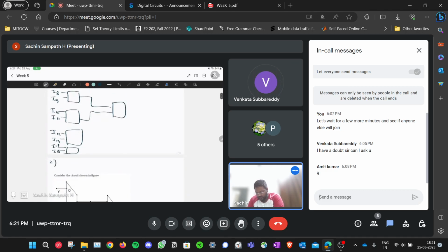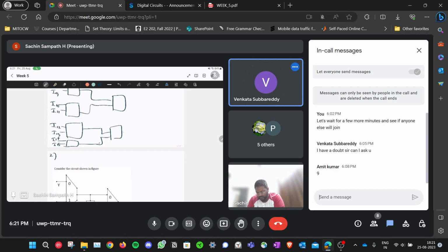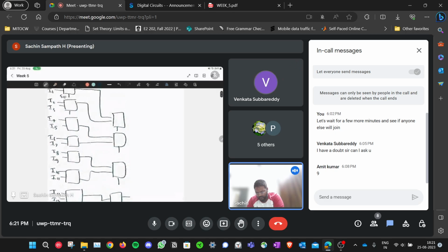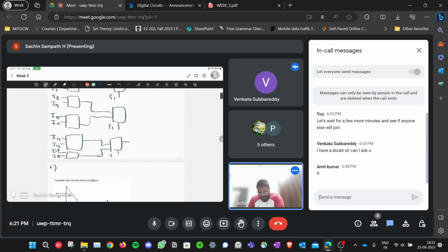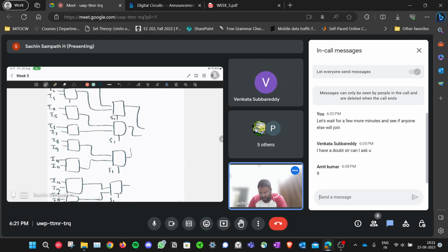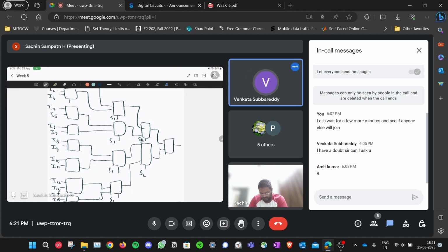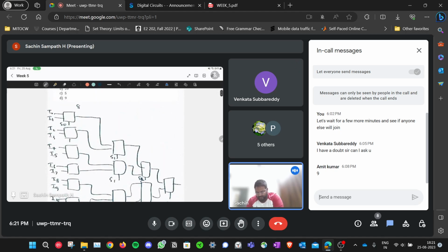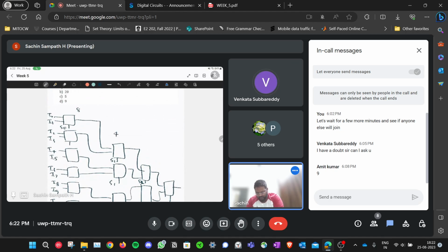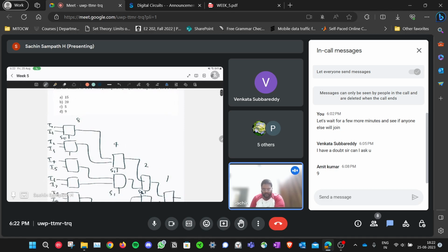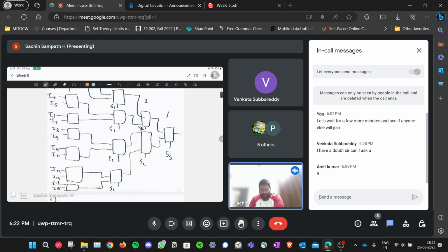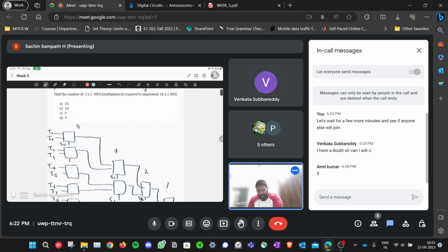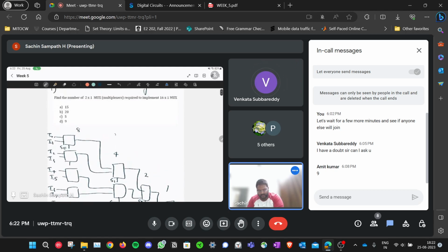Like this. And for each of these, the select line you will give is S1. Again you take two of these and feed them to one mux, and then the select line will be S2. Finally, this is S3. So this will be your 16:1 mux. As you can see, in the first stage you have used 8, 16 divided by 2. Then you have used 4, then 2, and 1. So the total is 15. Suppose, in the second stage, instead of using 2:1 mux, you had an 8:1 mux. Then you could simply use that one, an 8:1 mux. So you need only 9 multiplexers.